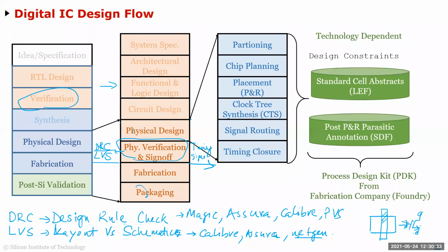So the delay is 110 picosecond and so on, and you do the timing analysis based on that. After it does the place and route and clock synthesis, signal routing and all that, there are tools which will extract, but now the extraction done is the SDF file, which actually just tells you the delay. The delay will be now, okay, no, it's not 102 now because there was a long route. It's actually 150 picosecond. And because of that, your entire timing is off completely. And that's also part of a file which is generated during this physical design process.